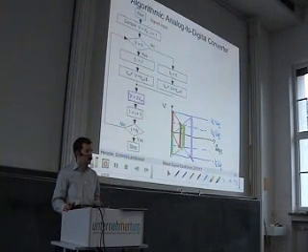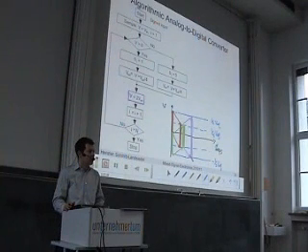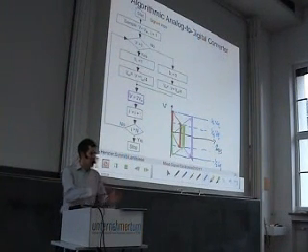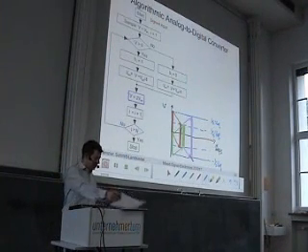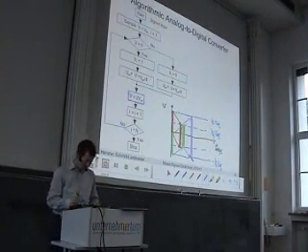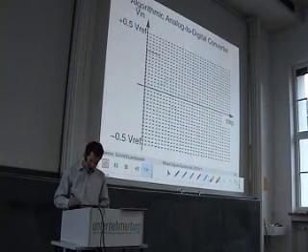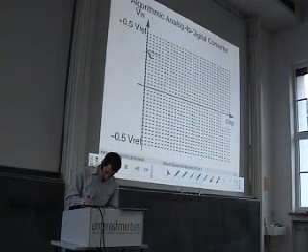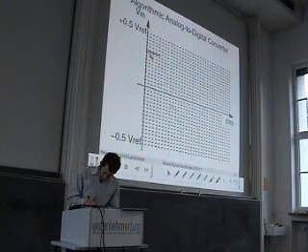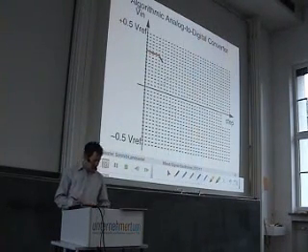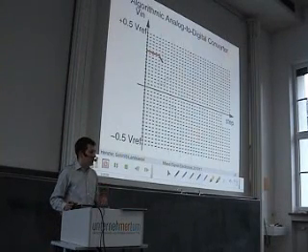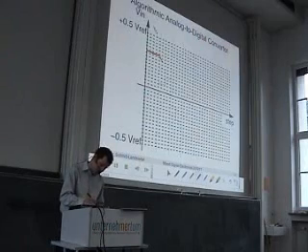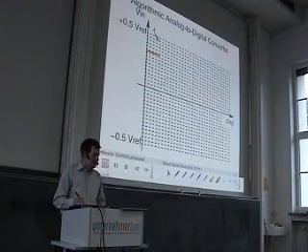So no need to scale down the increment or decrement or do something like this, just by scaling up the remainder and bringing it to the original interval. So we can exercise this also for an example. We can say we start here. Well, now we are larger than 0. So we set this equal to 1 and we decrement it by Vref over 4.